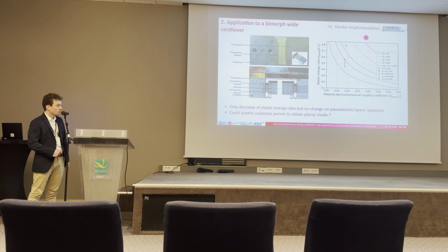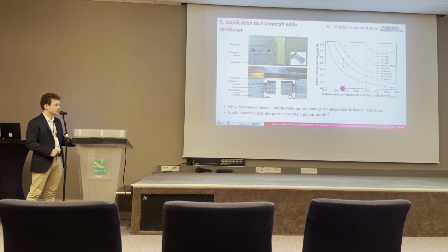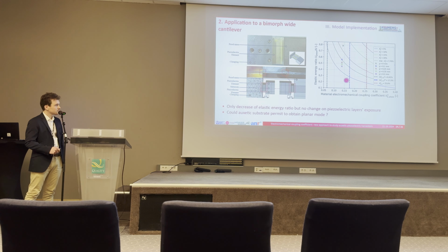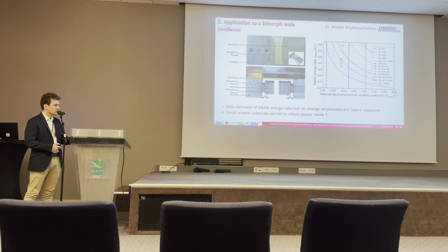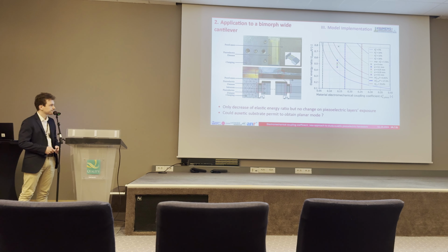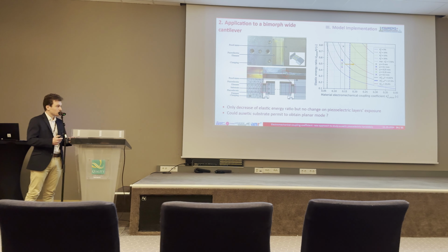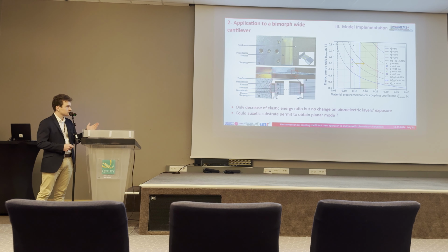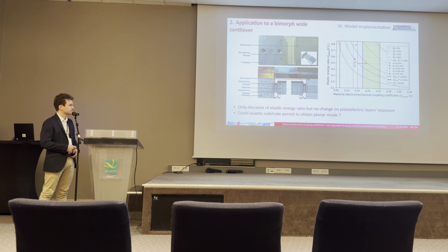And we see that the more we increase the gap, the less energy ratio we have, but the coupling coefficient remains the same. If we compare it to the theoretical values we had earlier, here is the long beam, wide beam, and planar mode. We see that we are over the long beam coefficient, but lower than the planar mode. So we would like to have these results in this orange part.